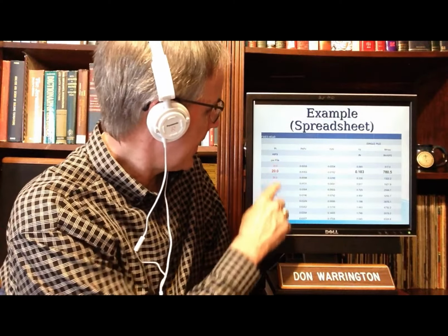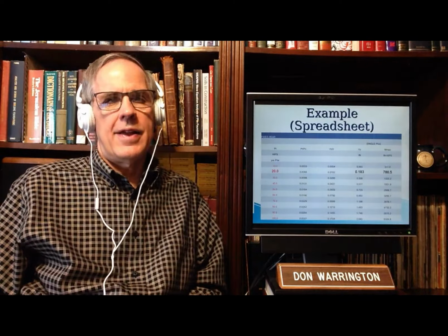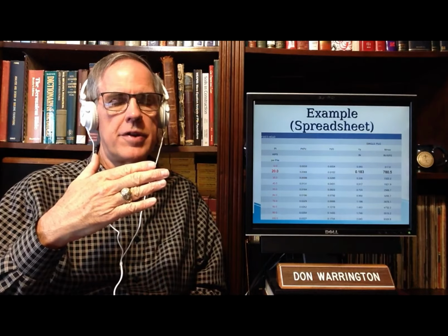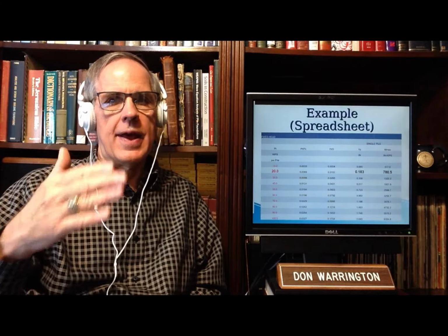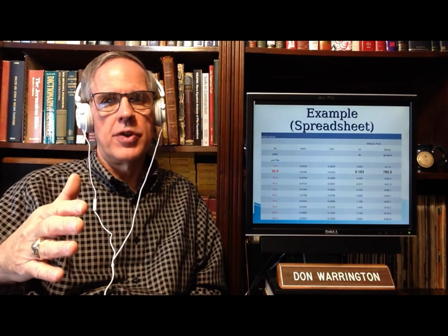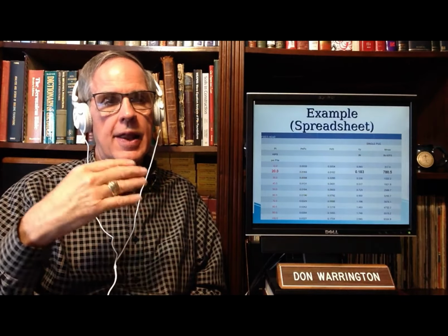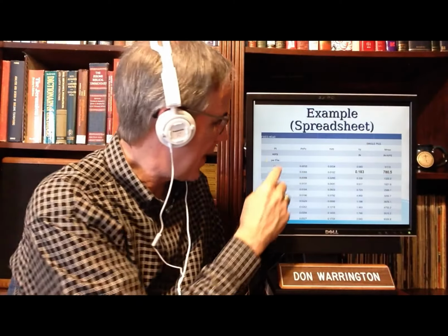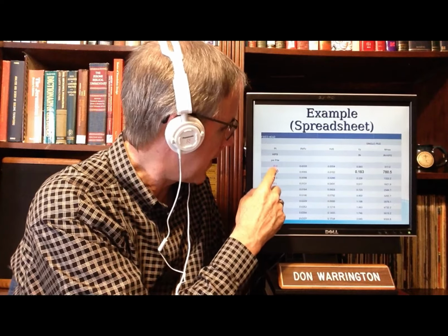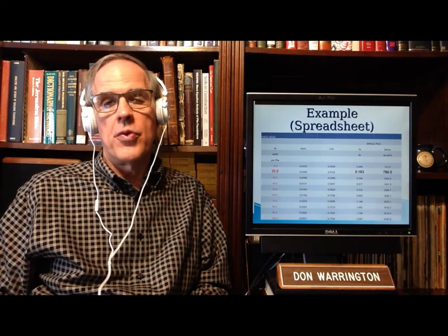Now, putting in the kips per pile, lateral loading is kind of like settlement. Your ultimate objective is to put in a figure for your loads, and then it will give you the deflection. And it allows you to put in any number. In this case, 1, 2, 3, 4, 5, 6, 7, 8, 9, 10 different loads. I only ask you for one load.